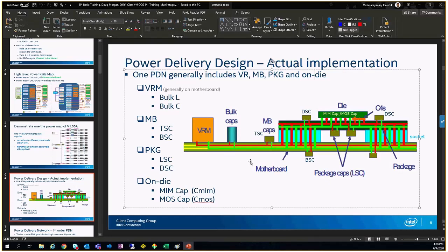The second is we have to have the capacitors, right? Generally for the cap models, the whole PDN network, starting from the caps to the package top, we get this modeled via Power SI. In Power SI, we load the board layout, as I showed last time. We merge it to the package. What we do is we form ports on the capacitors, all the caps.